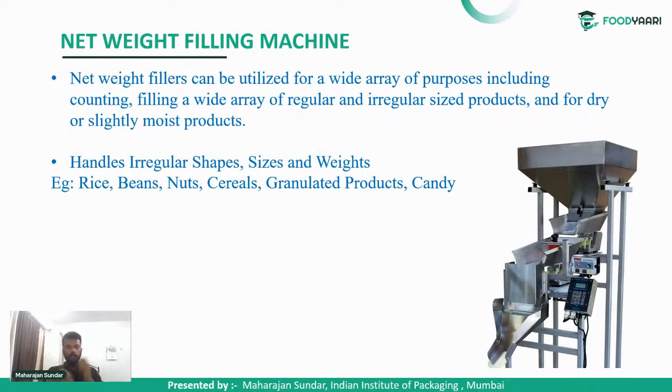From the hopper, as per the computer setting, it permits a certain amount of product to a load cell. A load cell is generally a weighing machine which actually weighs the product. For example, a 100 rupees or 50 rupees chocolate packet weighs around 200 grams. In case of 200 grams of chocolates, a single unit will fall on the load cell. After weighing, it will fall onto the packaging material, which is opened by mechanical means.